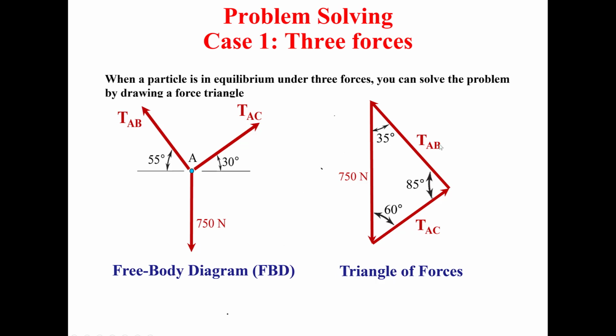So this way I draw what? The triangle of forces. After you draw the triangle of forces, you will adopt the method for the triangle of forces. You look at the situation you have, and we covered that in lesson number 2, where you have a triangle of forces and you decide when I should use the sine law or the cosine law. This will give you the solution, and you'll get a very accurate solution because you have only 3 forces meeting at a single point.